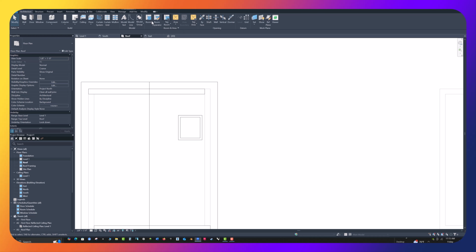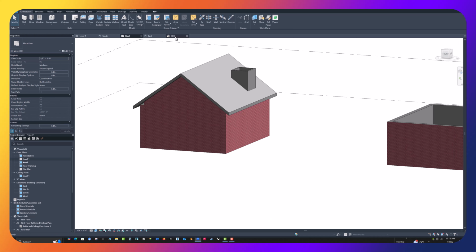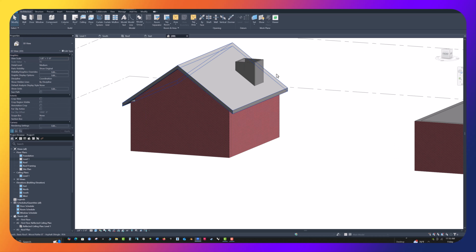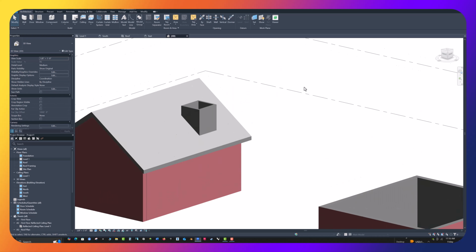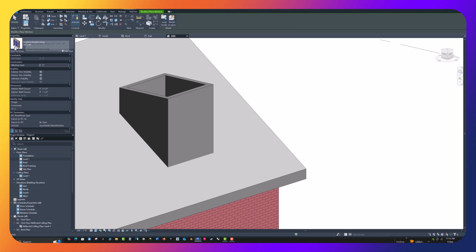I think I'll go to the 3D view, would be the best place to see it. So there are my walls. I want to go ahead and put a window in here. That's what a dormer's for. So I'm going to grab my window tool and double hung 36 by 40. Yeah, that works. So let's drop that guy in there like this.